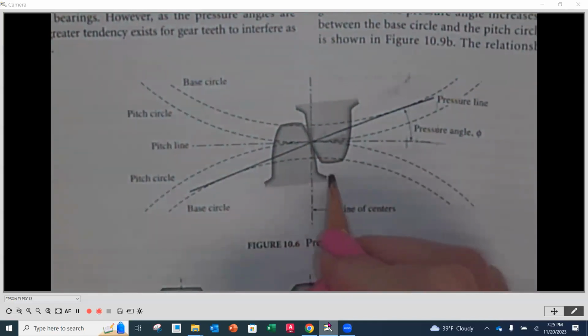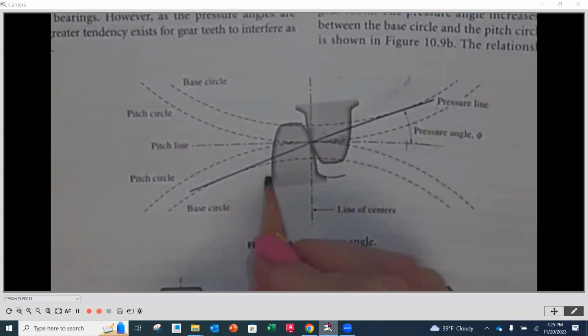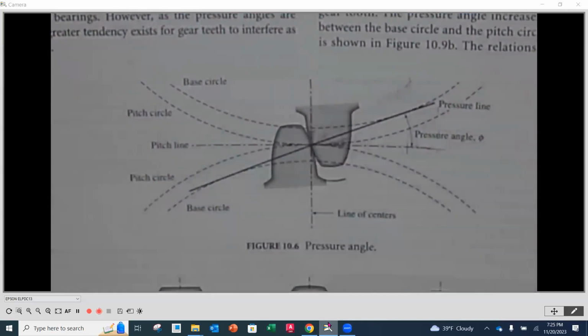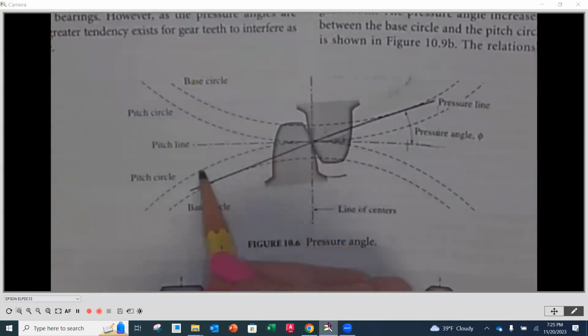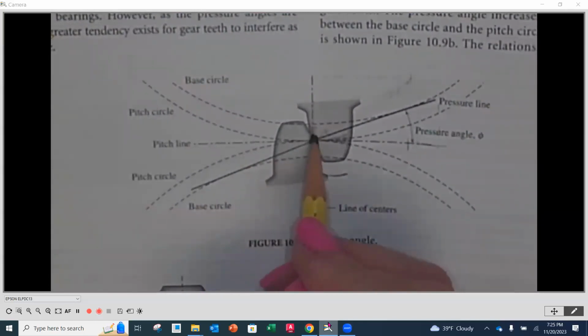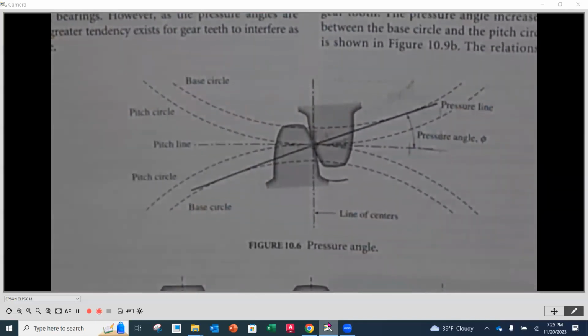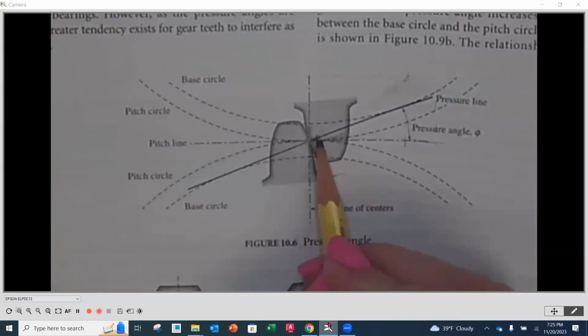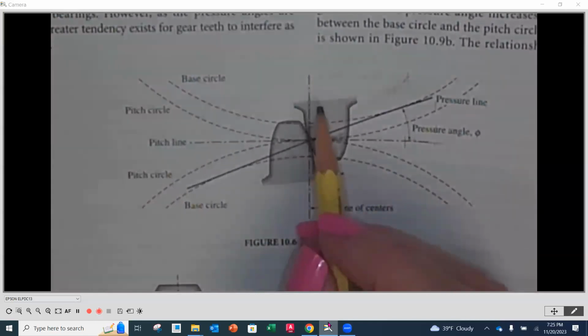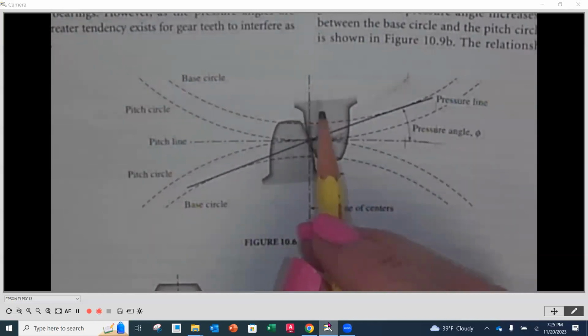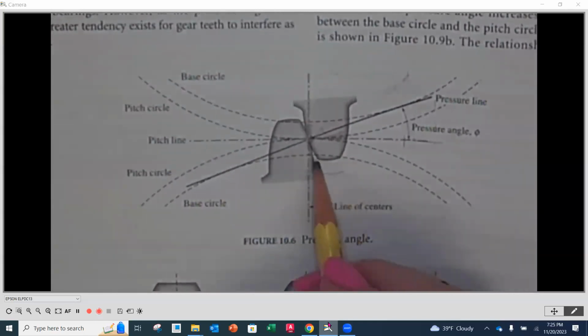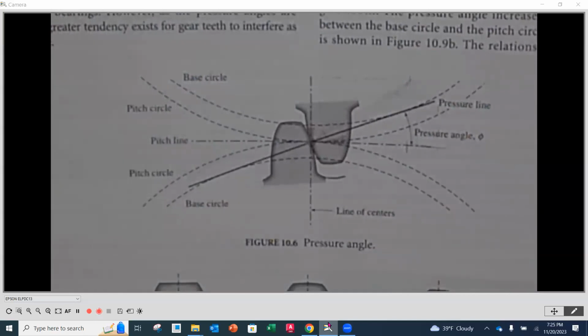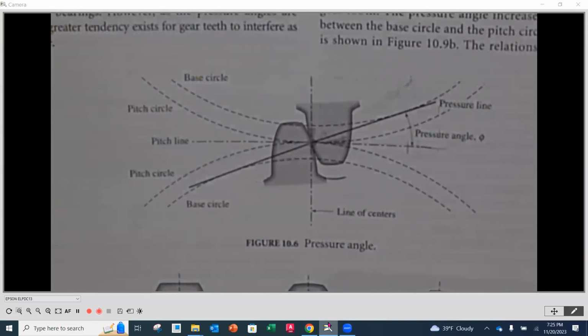If this would continue, this is the dedendum down here, and this is the next tooth coming in. This circle is the pitch circle, the point of contact for those two teeth to be engaged with one another. It's also important because at that point the addendum is actually shorter than the dedendum, and that's by design, because we don't want it bottoming out or catching the bottom of that tooth and interfering.